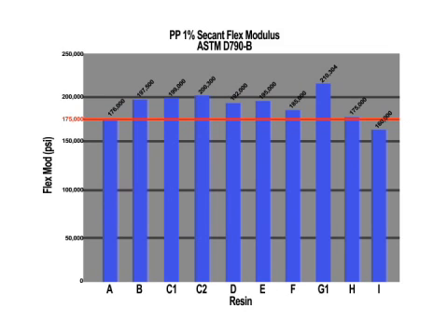The reason I show that is to represent to you that we have an internal process by which we qualify and disqualify resin types. In this particular case, this was a test resin that we had looked at. The value was 160,000 psi for flexural modulus, which would show that we would disqualify that as a resin.